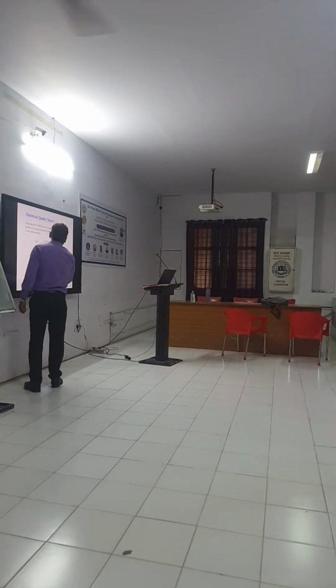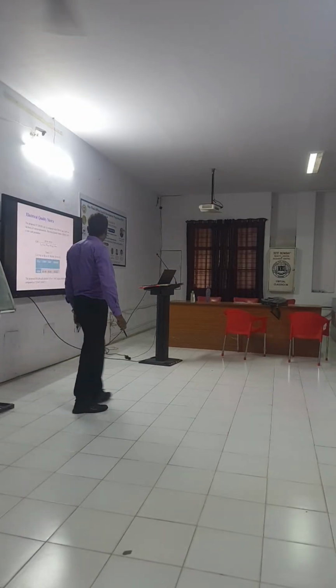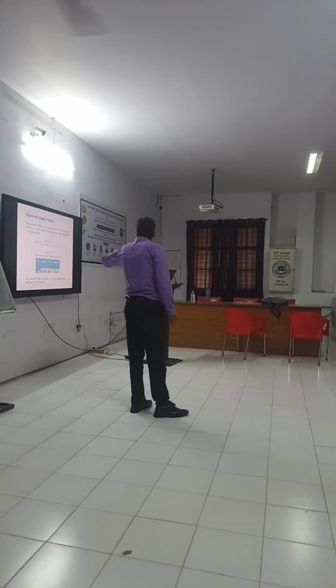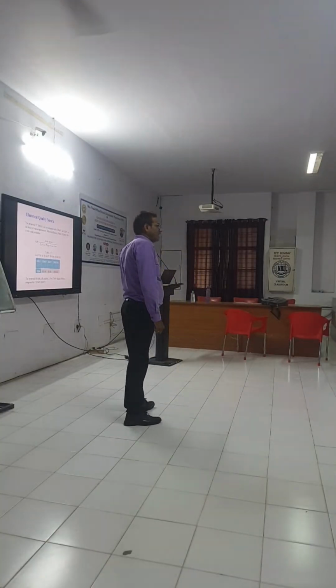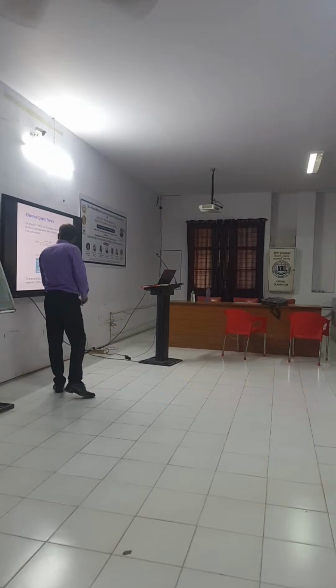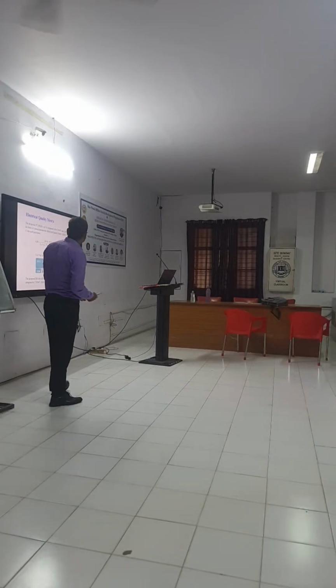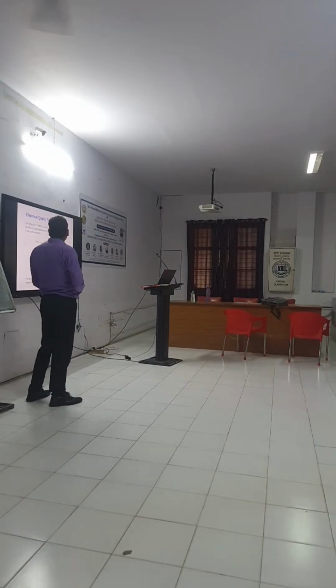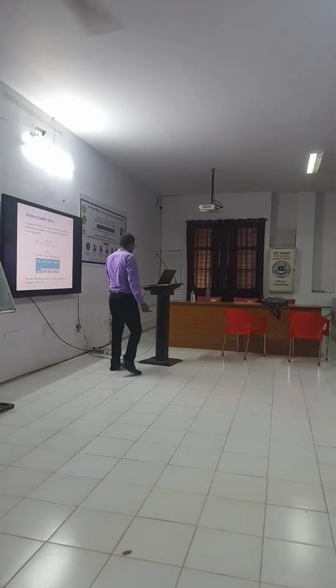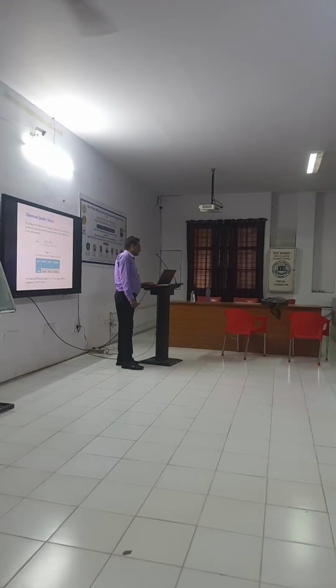Conventional it is 82, zigzag 38, and ours 292. So this represents that a higher quality metric means a better circuit. Okay? So this proposed cell exhibits 3.5 times higher quality as compared to the conventional zigzag technique. So no doubt this one will be acceptable.